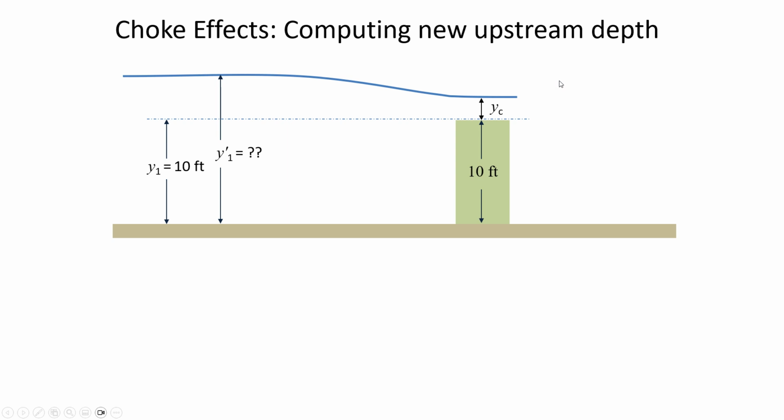So here, why would the water flow at anything other than the critical depth? Because the critical depth is the most efficient depth for a given flow rate. So the reason why pooling occurs and it stops pooling once the water is able to flow at the critical depth, is that the critical depth is associated with the minimum amount of energy required to get the water over the obstruction. So that's why it flows at the critical depth.